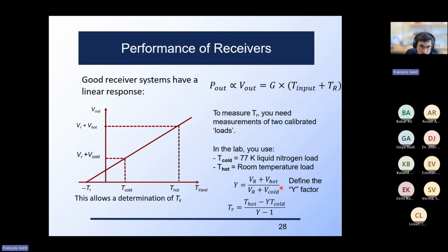So in operation, we also view the sky, and we use a very simple atmosphere model to calibrate the opacity of the atmosphere in order to go from the receiver noise temperature to the system temperature. The one note to be made here is that depending on whether you measure SSB, single sideband, or DSB, when we quote the receiver noise temperature, we have different limits.